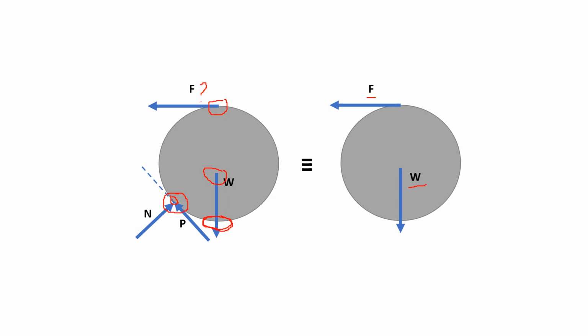So what is the repercussion of the wheel being a three-force member? We see F here with a known direction and a known point of application. We also see here W with a known direction and a known point of application. What we will do is connect the line of action of W with the line of action of force F. So a horizontal line of action and a vertical line of action connect at this point.